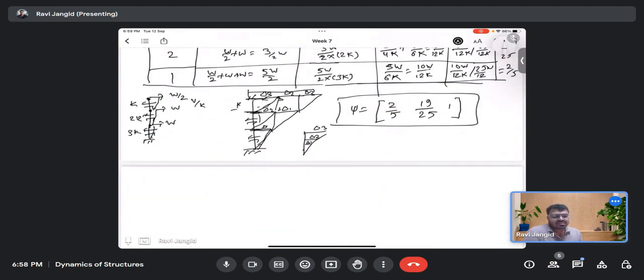So after getting phi x, you need to find out the generalized mass, generalized stiffness, or the K equivalent. Because here we have the ground excitation ug, there is one factor if you go through the lectures, L, the load excitation factor. So first find out the M equivalent. That is the same, sum of mi phi i square. So mi is what? M by 2,